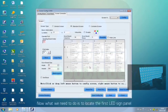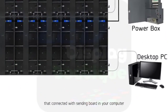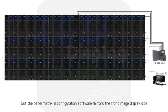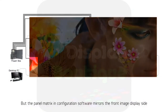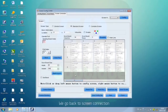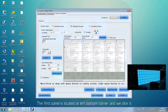Now what we need to do is to locate first the LED sign panel that is connected with the sender board in your computer. You can see the first LED sign panel at the bottom right corner, and the signal goes through all panels along the red line, but the panel matrix in the configuration software mirrors the front image display side. Now the first panel is apparently at the left bottom corner, and the signal goes through all panels along this red line. Now we go back to screen connection, as it mirrors the front side of the LED screen. The first panel is located at the left bottom corner, and we click it.